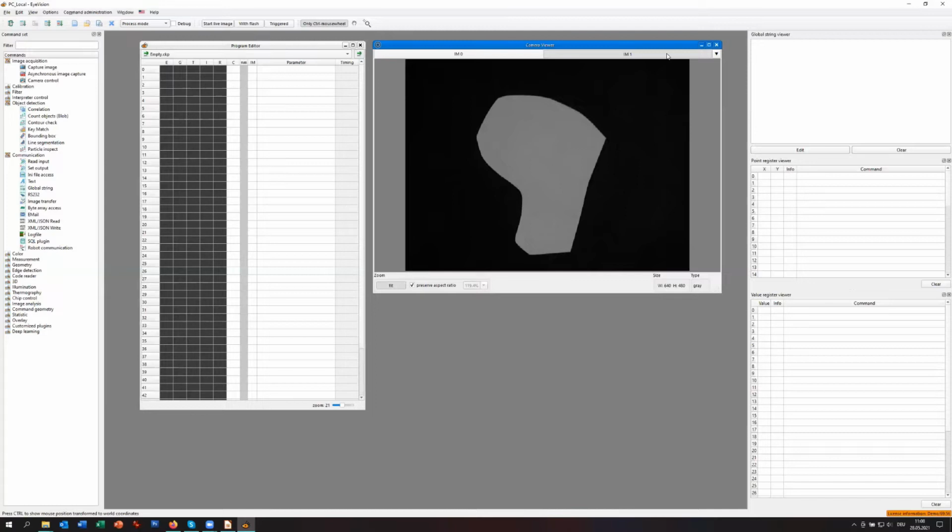But you want to be sure each time you start the software that if you have multiple cameras, they are connected to the same image memory. So you have the option to assign them to each image memory. So maybe you have one camera in the robot hand and the other one for the overview. Then you could have the robot hand in 0 and the overview camera in 1.